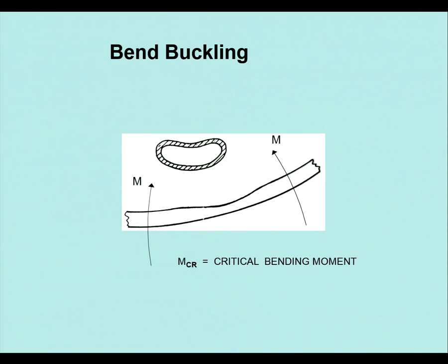And this is reinforcing bars. What they'll do is they'll ignore the tensile, say that's got no strength whatsoever, and we'll work out the shift in this neutral axis. So this is compression, compressive side, and this now will move down here. So what's going to happen to this is going to be like that, through the pipe, and there's the concrete coating. Your neutral axis has come down here.